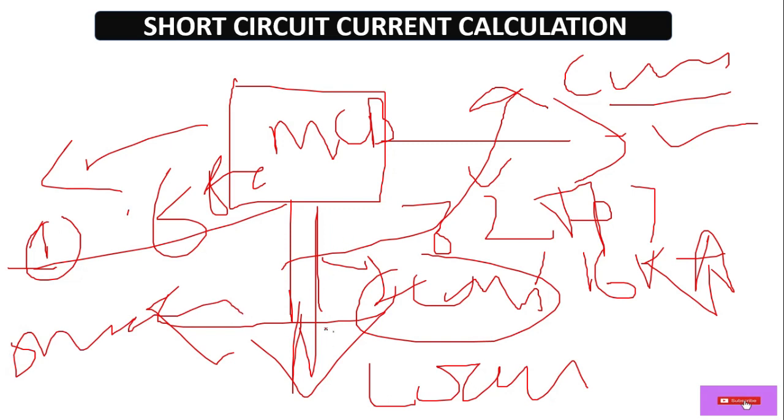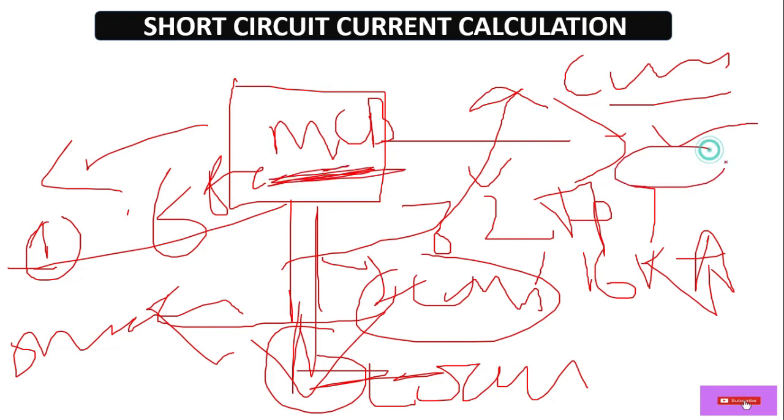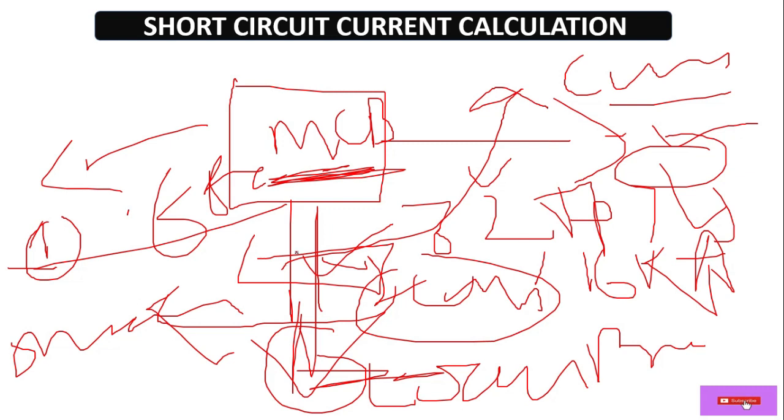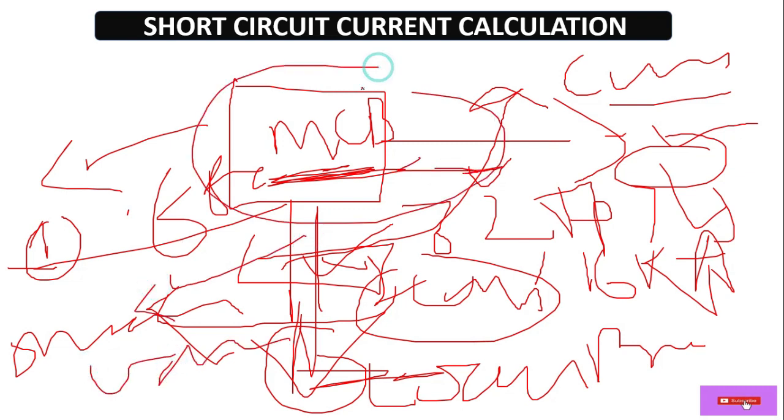As per this connected load and the MCB short circuit or breaking capacity rating, the cable must be able to withstand it or not. Suppose we select a cable under the breaking capacity of this breaker. In that condition, during a fault, this cable will be burned. That's why we need to consider the short circuit current as well.